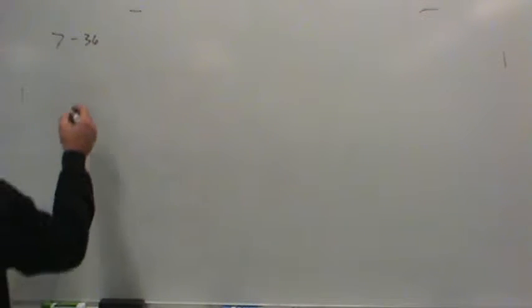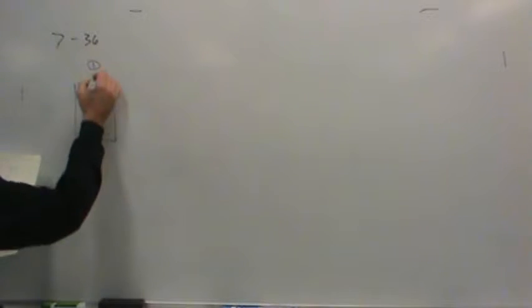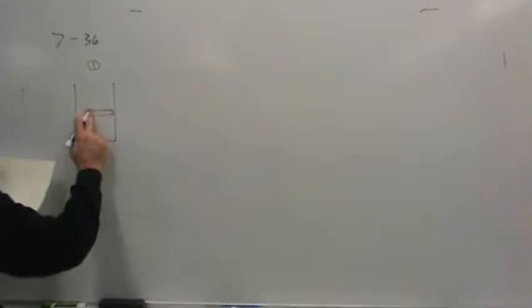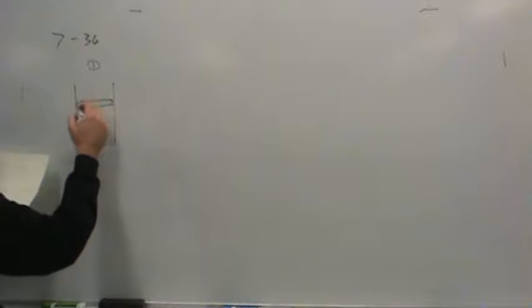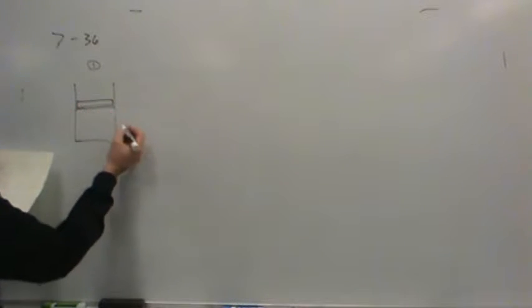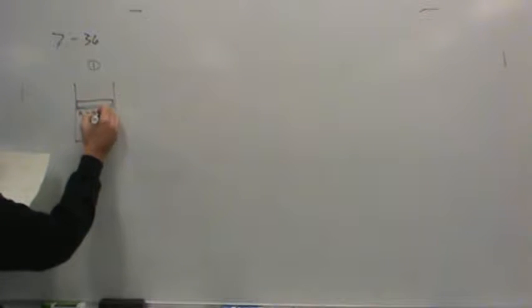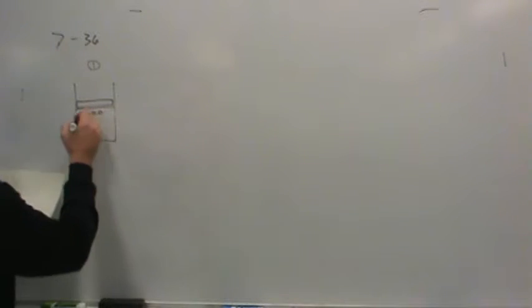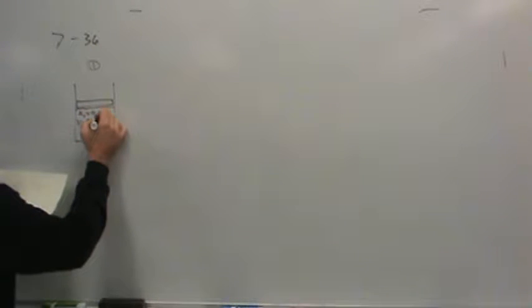Okay, so it's an insulated piston cylinder device. Let's draw it in both states. Here's state 1. Probably need a little more space than that, so let's move it up a bit. There's saturated liquid water. So if this is state 1, that means that the quality in state 1 is 0.0 because it's saturated liquid. The volume is initially 5 liters, which is